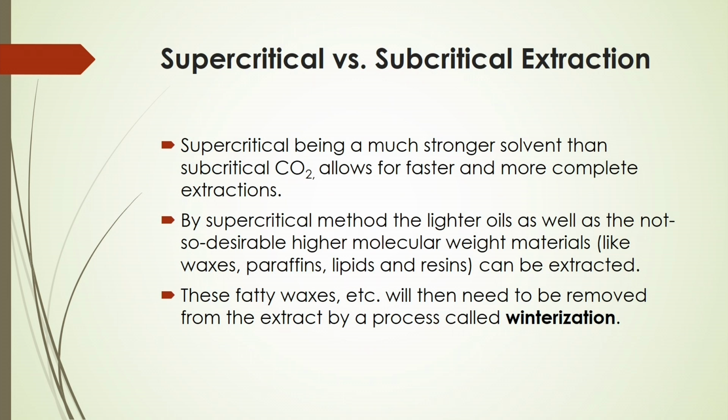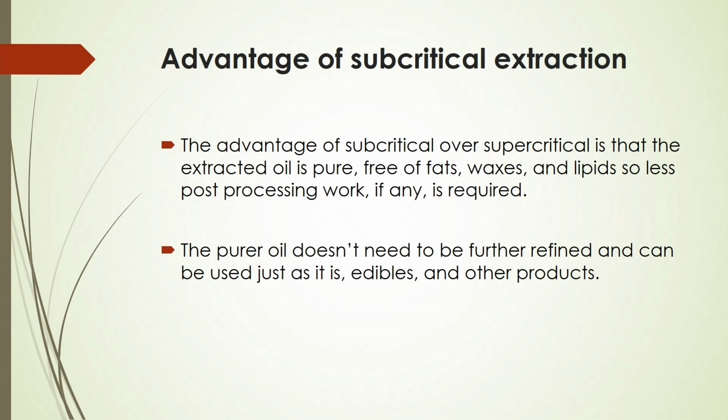And these fatty waxes etc. will then need to be removed from the extract by a process called winterization. The advantage of subcritical over supercritical is that the extracted oil is pure, free of fat, waxes and lipids. So, less post processing work, if any, is required, and the purer oil does not need to be further refined and can be used just as it is, in edible and other products.